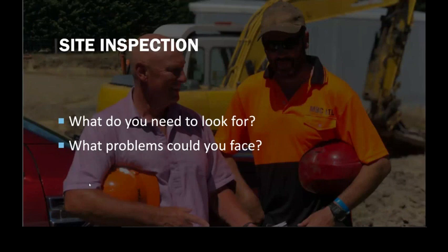And then you need to go and check out site conditions, because it can be quite different for different sites. Some might be nice and flat with sandy soil. Other places might be on the side of a cliff, in Wellington somewhere. It's all rocky and clayey, and it's a very difficult site to work on. So you need to get a grasp of that. Plans can give you some of that information, show height changes, things like that, but they're not going to give you the actual site conditions.